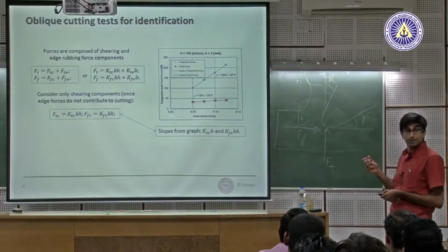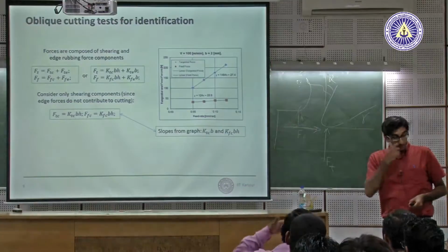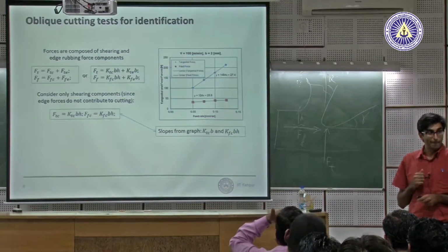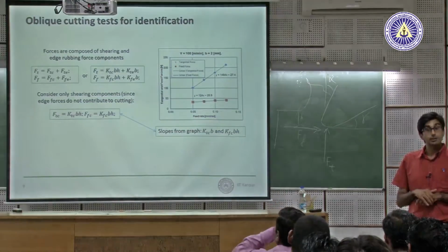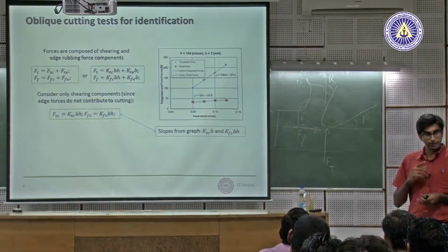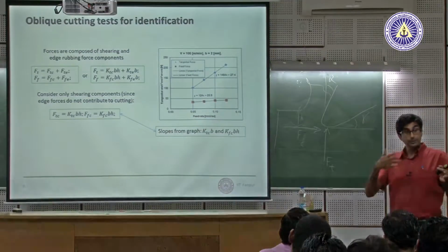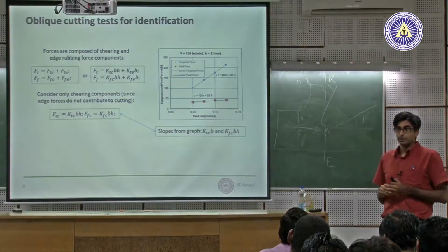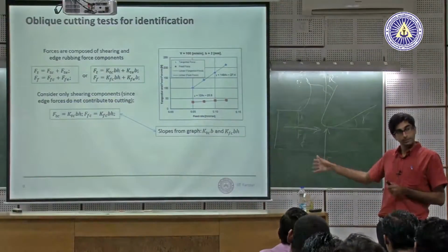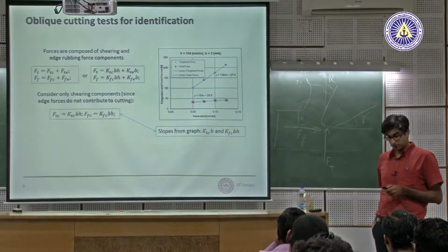So that's what. Sorry? No, so there are many different models. This is one model where we fit a straight line. There are other models called the Kienzle model where you can fit exponents, which is actually more real. But if you're doing it for a given set of cutting parameters, this works best. It's easiest to do. Yeah?